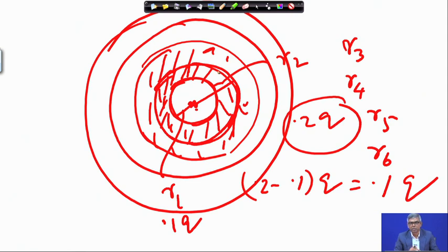So, we have shown that for 0.1 q, 0.2 q, 0.3 q, 0.4 q like that, you have got the corresponding r by z. Now, I have fixed the z, so I draw the corresponding r1, r2, r3, r4. With those radii, finally r equal to infinity will be the last circle. So, between two circles, the influence at the center at the constant depth of 2 meter will be the same. That means each annular area's effect at the center will be the same. That is the important observation to be used for drawing the chart.